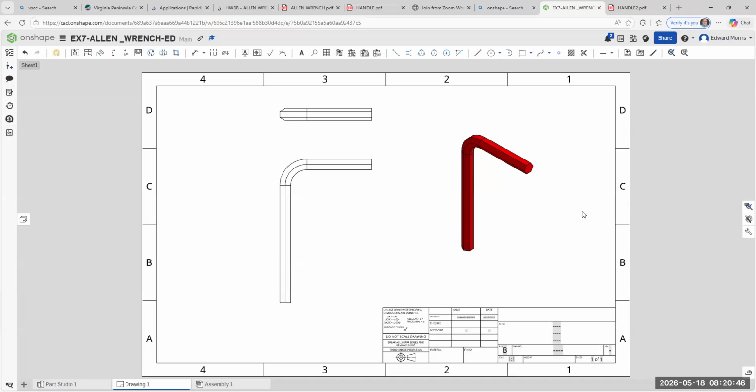You doing okay? All right. Now you know we need to put our labels in there. So go, well, I guess we probably should dimension it first. Sorry. Mr. Morris is getting carried away. So go to the dimensioning tool right here. See this one? And we're going to dimension from this point to this point. You're going to bring out the dimension. I don't know if it needs to be 3 decimal places, but that's okay.